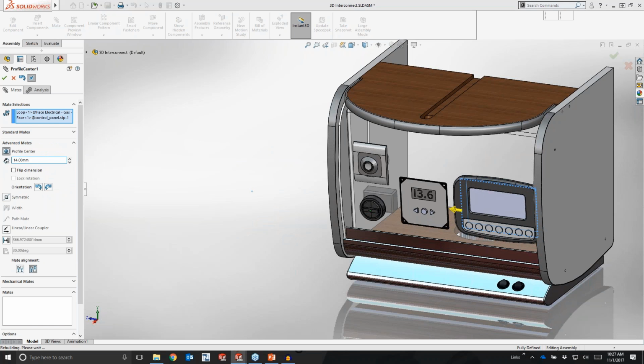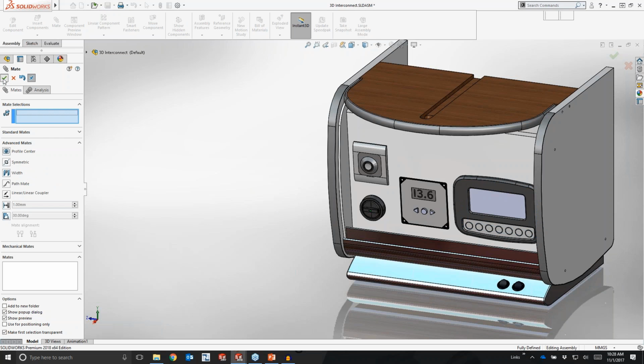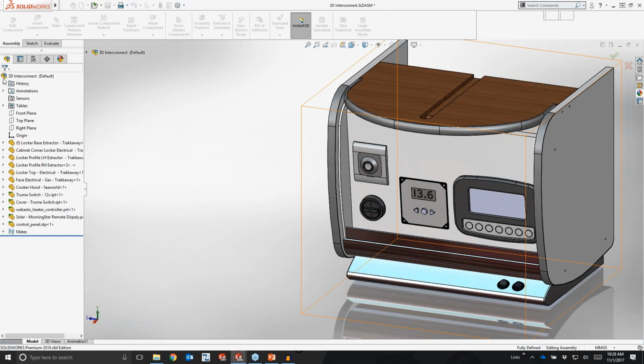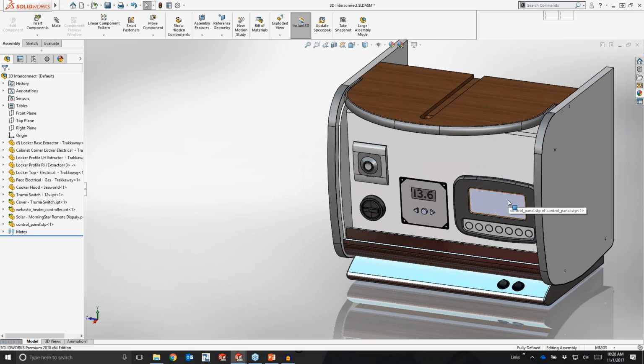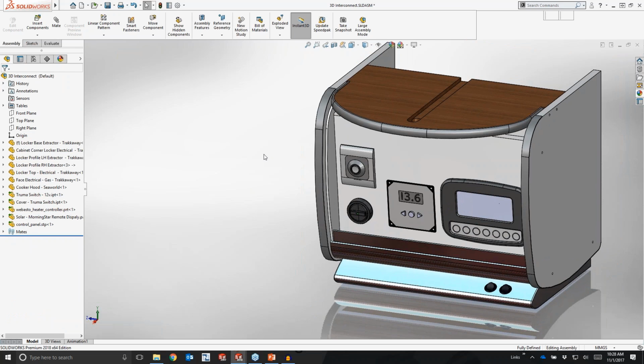Now, if this was a native, let's say Inventor, Pro-E, or CATIA file, then it would very easily be able to be updated in its native package, and then those mates would be reattached on the other side. But because this is a neutral step file, it's not going to be able to reattach mates, but it does not require that conversion process.